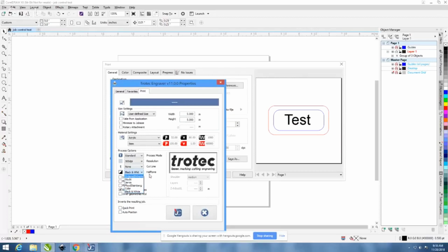John, I guess the invert you'd really use for, if you're engraving any black acrylic or granite, like a photo engraving, you'll have to invert the colors, right? That's really what it's basically there for. Exactly, yeah. So on a piece of black marble, for instance, the engraving is white. So you actually will want to invert your image so that the areas that turn out white on the piece are the areas that are actually black in your engraving. So that's why you would want to invert it.